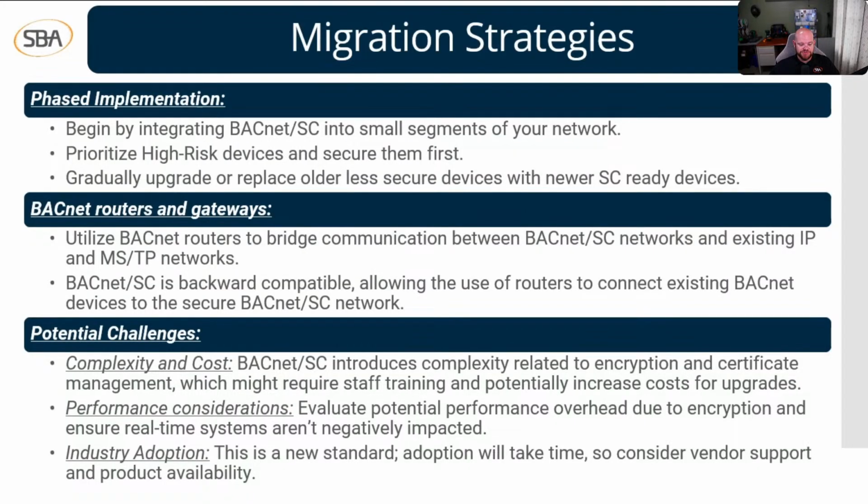So BACnet SC introduces complexity related to encryption and certificate management, which might require staff training and potentially increase costs for upgrades. So you may have more training time in this as well. So these are all things that you need to think about and talk with your leadership and figure these costs in beforehand. Next thing is the performance considerations.